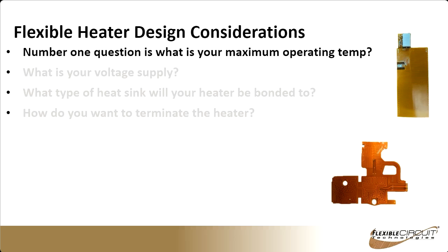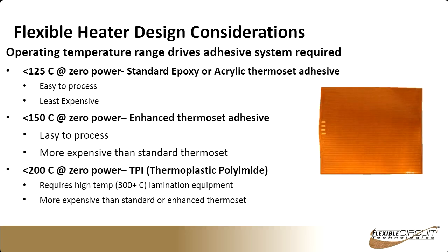So when you have a new flex heater, the first question I'm going to ask is, what's your maximum operating temperature? And that's going to drive the type of adhesives that we use to bond everything together. And you can see that there are 3 different options that we currently have. And you'll notice that each one of them is designated at 0 power. And I'll get into that a little bit here in just a few minutes also.